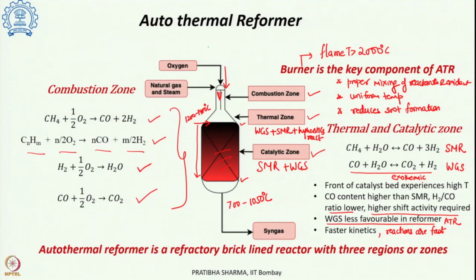How does the autothermal reformer work? For the natural gas, one chamber is used, one autothermal chamber. The input gas is natural gas, CH4, and steam, H2O, and oxygen as oxidant. Oxygen will also help in burning, producing the heat energy which is required for the reactions.